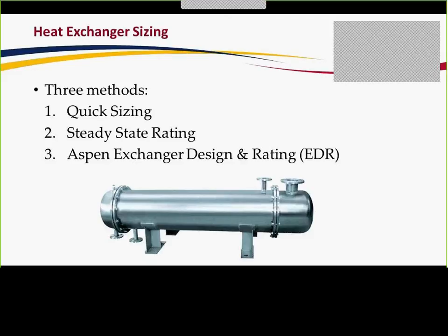to put which fluid. And we used a steady state rating for some of those, and that involved first quick sizing the heat exchanger, and then inputting that area into HYSYS, and then varying the parameters until we received what we deemed was an optimized model. The final way of sizing was the EDR method, and that was just putting in a few basic pieces of information into HYSYS, and then using the simulation software to size the equipment for us.